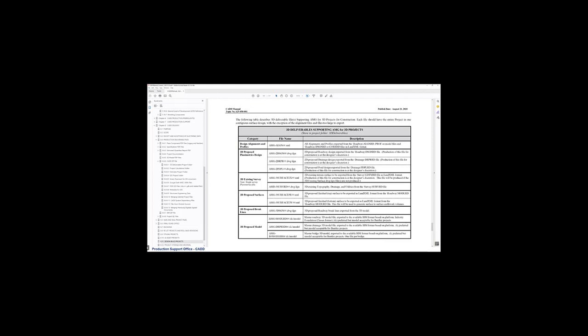The 3D proposed models, so this isn't in the order that we're going to be creating them in. There's a different order, and there's a reason for that. The 3D proposed model is going to be coming from the master model file because it's the entire model, all the models in one federated model essentially.